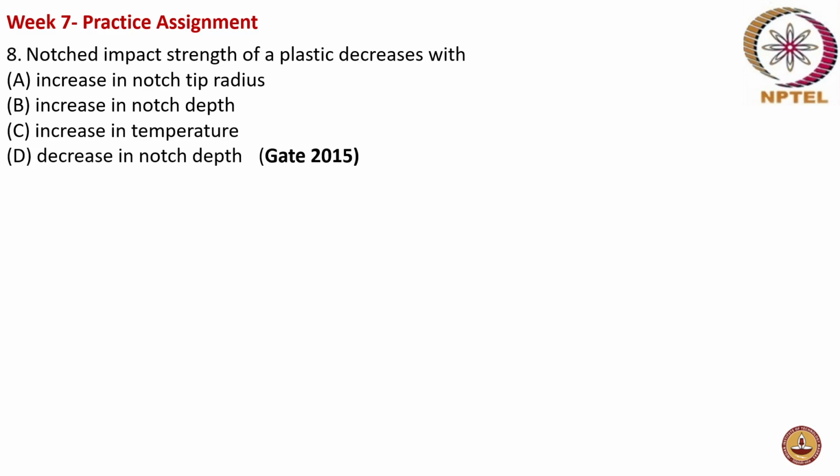Notched impact strength of plastic decreases with increase in notch tip radius, increase in notch depth, increase in temperature, or decrease in notch depth. Which one of these happens?